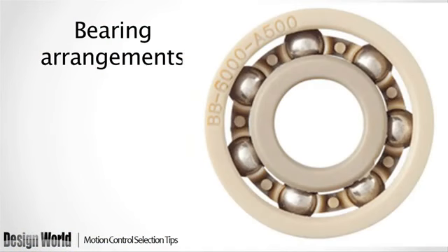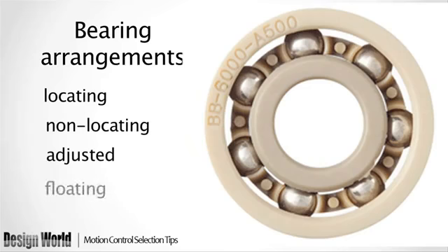Lastly, consider the bearing arrangements. Commonly specified arrangements include locating and non-locating, adjusted, or floating versions. You can choose from a wide range of locating, non-locating bearing combinations to achieve specific performance objectives consistent with application demands.